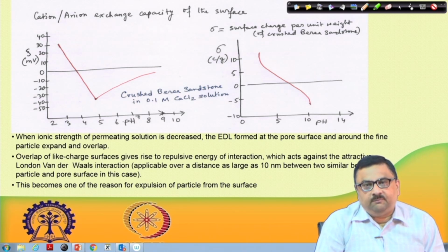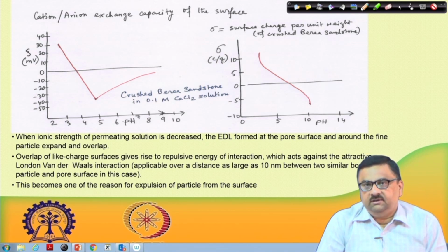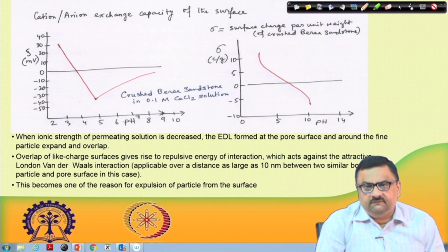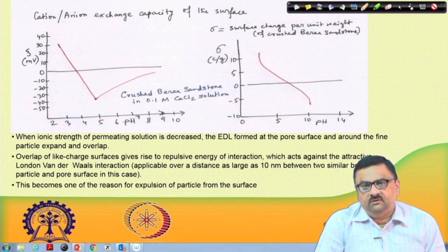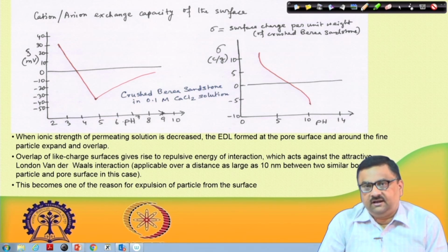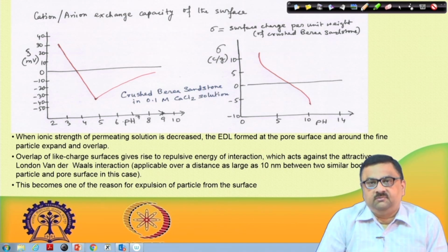We have talked about the electroosmotic pump, where glass beads are used to create a porous medium, and by application of a voltage a very controlled flow rate can be achieved. The reverse of it is streaming potential. If we do not apply voltage, but rather a pressure gradient, then because of the electric double layer formation, with charges accumulating near the wall, one develops a streaming potential, which can be measured as a potential drop across the porous medium, and we have talked about that as well.